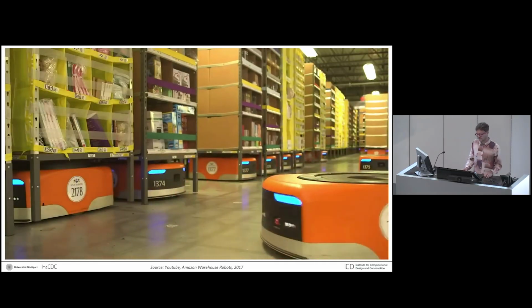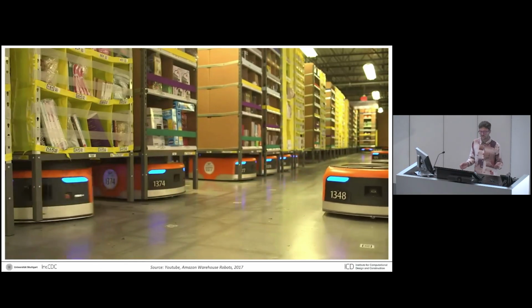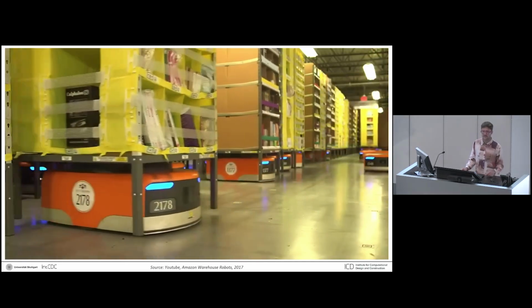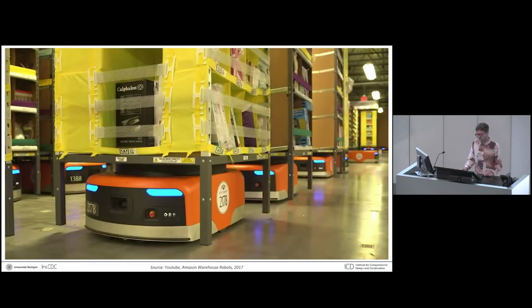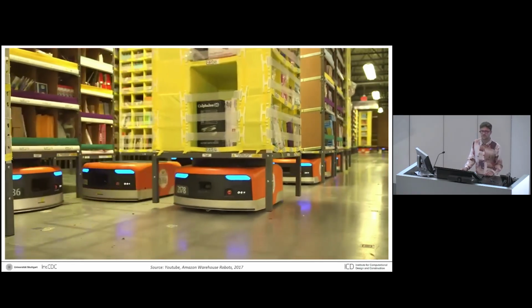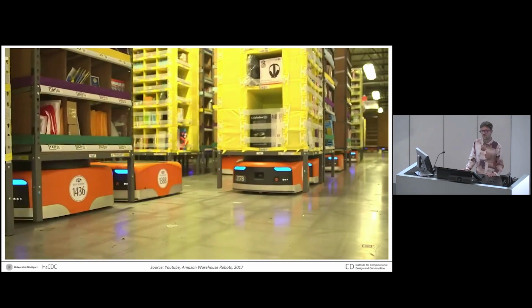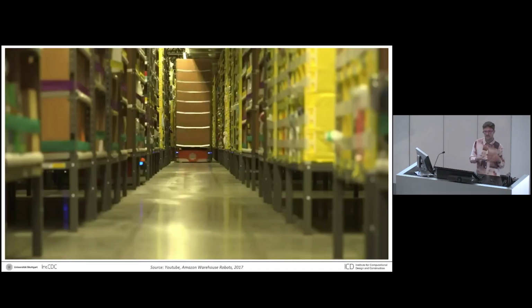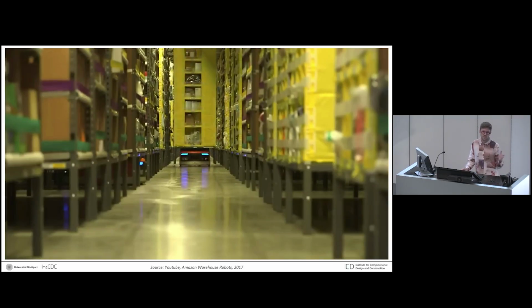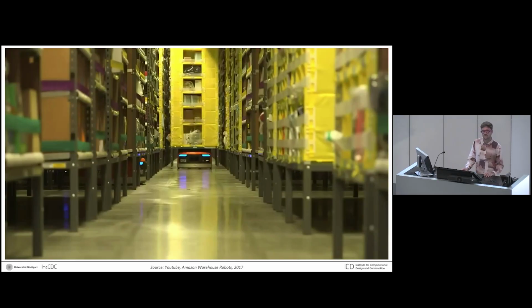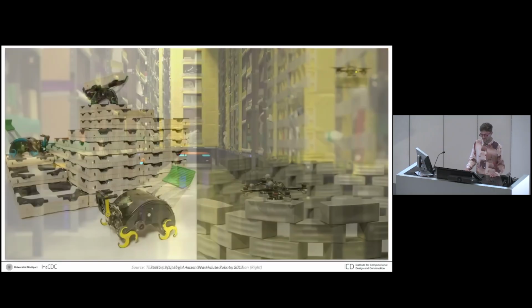There's a couple of names for this, and these systems are teams of mobile robots which solve complex tasks using their shared intelligence. And as compared to other forms of robotic automation, these systems have the potential to do a couple of things. First, boost the overall flexibility in that they can move around, increase fault tolerance, as if one machine breaks, another one can take its place. And as compared to a lot of the other machines that I showed, these tend to be a lot more inexpensive, so generally reduce the cost of the automation system.